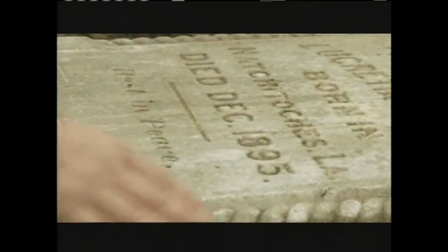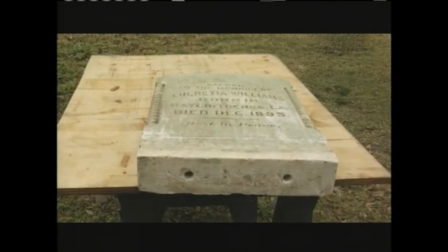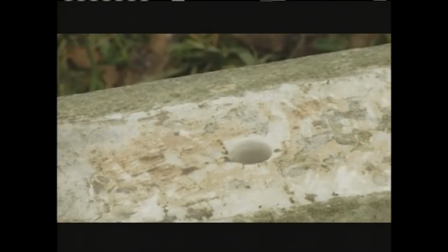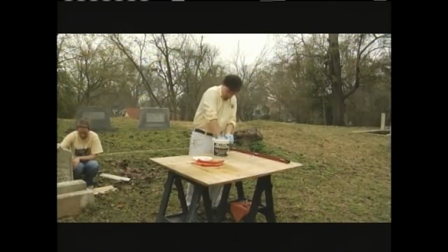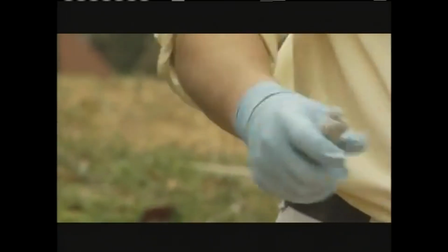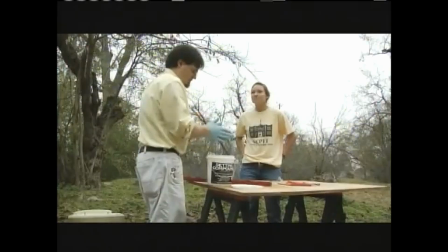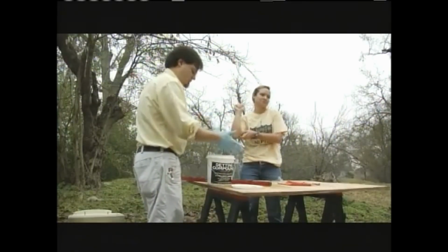Now that our stone is dry, we can prepare the base for the headstone. It is always a good idea to dry fit the stone before placing any compounds or mortars to assure a tight fit. For this reset, we're going to use a Monument Builders setting compound. This material will stay flexible to allow the stone to expand and contract over time and will not break the bond. Also, the setting compound can easily be removed if needed in the future. This causes minimal impact to the historic stone.